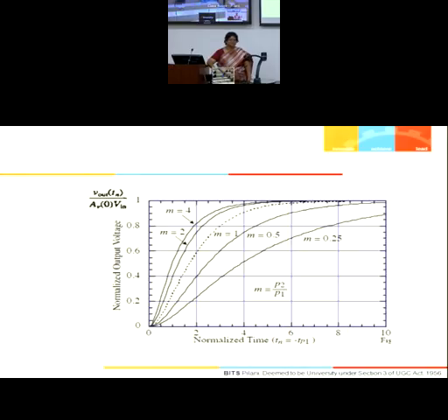Very easily we can say this because your 3 dB frequency will be less. Correspondingly, your 3 dB is the effect of two poles taken together. It is because of a combined system that the 3 dB frequency comes from the impact of all the poles in the system. And we know that it is usually less than the lowest pole. As a result, the response becomes more and more sluggish, or the time period becomes more and more large.